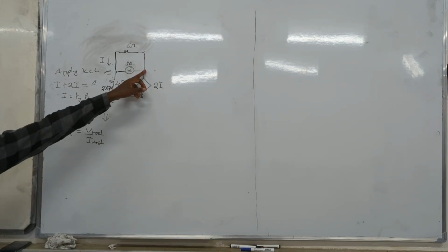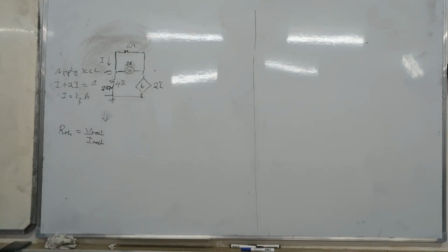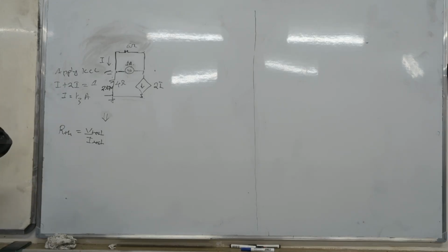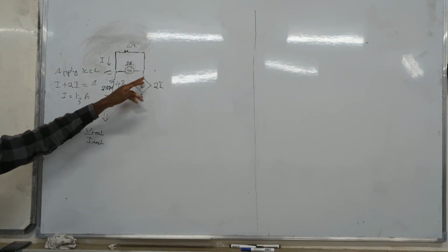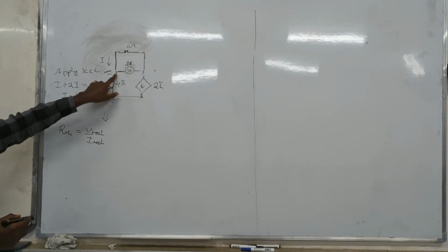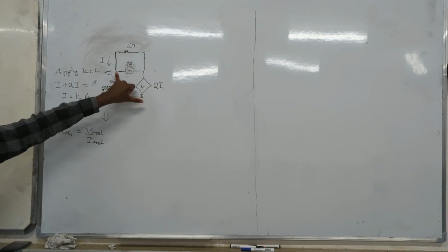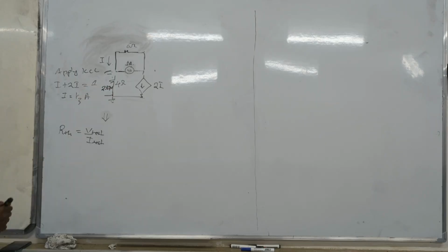If we walk from there, we'll find the what? A source. So this source has some, this is a current source, but you can think of it as there's some voltage. So when you move across a source, voltage changes. Although this is a current source, that's just the way of thinking about it. So this 2.67 is just across this point. So that's why you can't use this part. You use the other one because for the other one I can walk from.